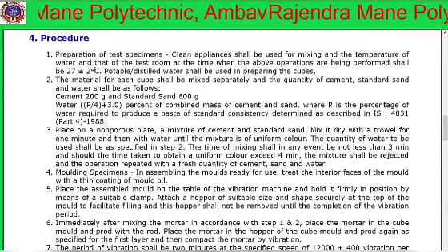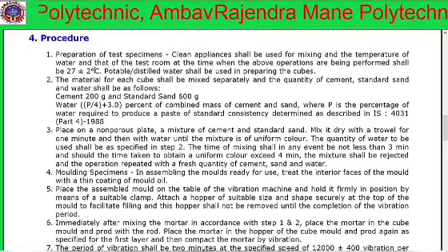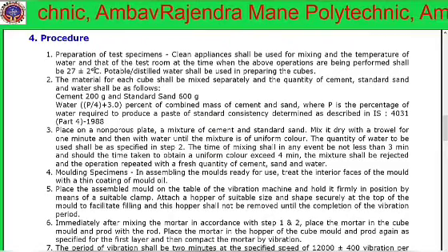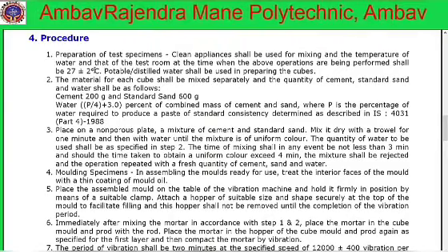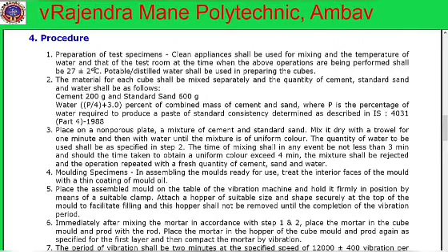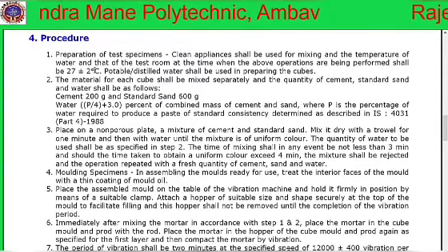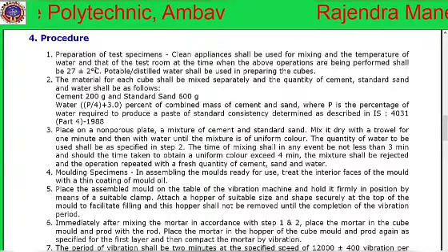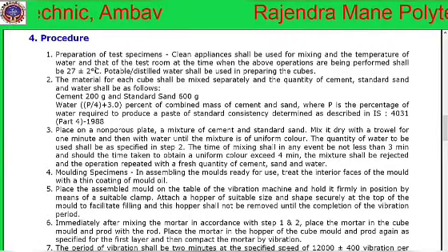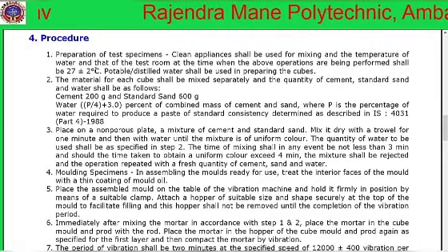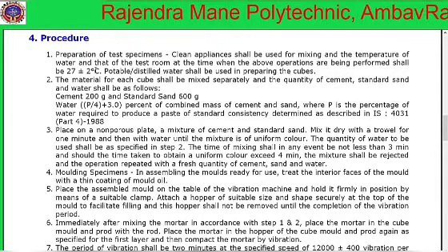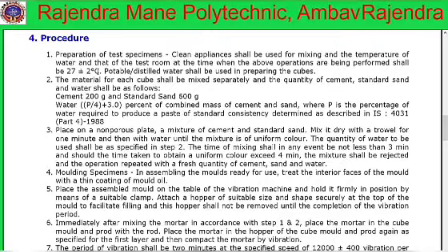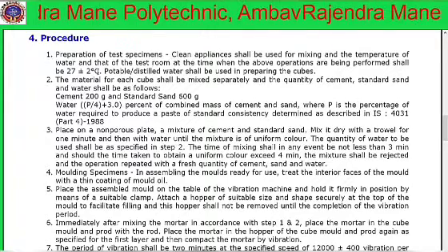The mixing time should be between 3 to 4 minutes. The mold is fitted on the table of the vibrating machine immediately after mixing and compacted for at least 2 minutes. This process should be completed within 5 minutes after the mixing of the ingredients of mortar.